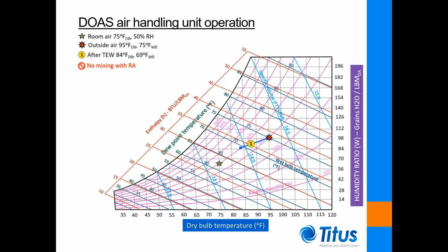The psychrometric processes involving a DOAS air handling unit are detailed here. As there is no mixing within the unit, the outdoor air mixture leaving the total energy wheel passes directly to the cooling and dehumidifying coil, where it is cooled and moisture is removed as previously described. In most cases, the condition of the mixture leaving the coil is the same as with a mixing type unit.